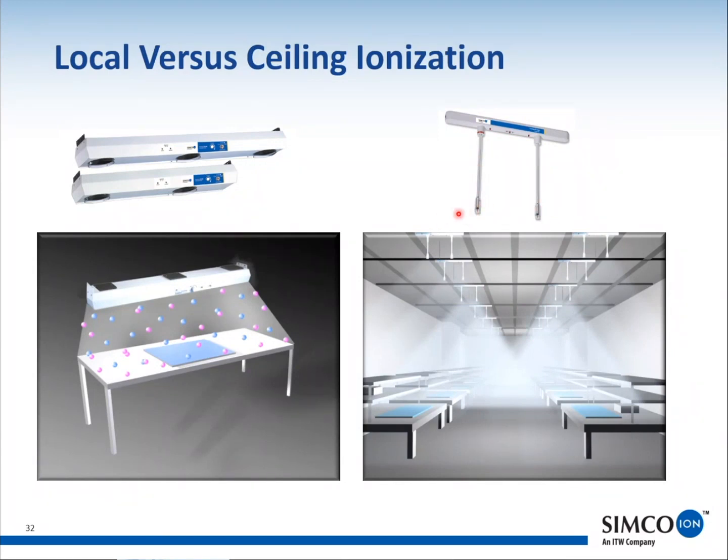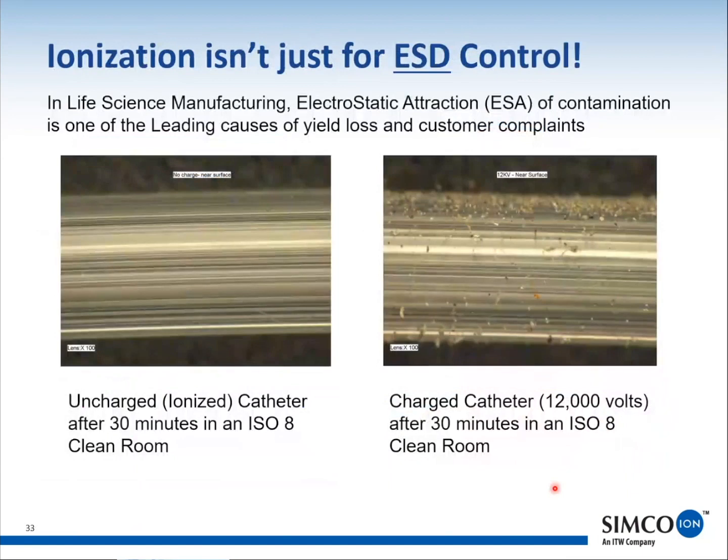It doesn't really matter, except there is a red stripe around the negative one, I believe. What this does is it cycles on and off, positive and then negative, and then there are some off times. We program them to take advantage of either a lot of airflow or very little airflow from the clean room. But you can see that we're going to ionize the entire room with this kind of ionizer, whereas with this overhead blower, we're just ionizing the workbench. Where we'll use that is in controlling charge and controlling particulates.